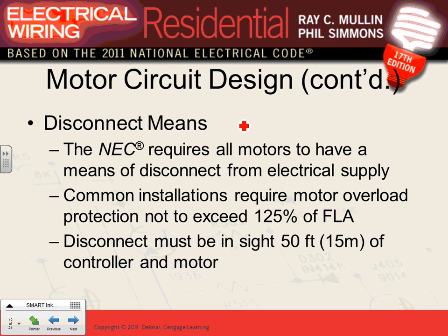Disconnects. Motors are rotating machines. We got sick of people losing their fingers inside machines, chopping their fingers and being killed. So the code decided we needed something to physically, mechanically isolate the whole system. After you kill the system through the pressure switch, you need to go to a disconnect like this one on the wall. You can clearly see it's on now. You can put it off, lock it, tag it, and do your work on the equipment.